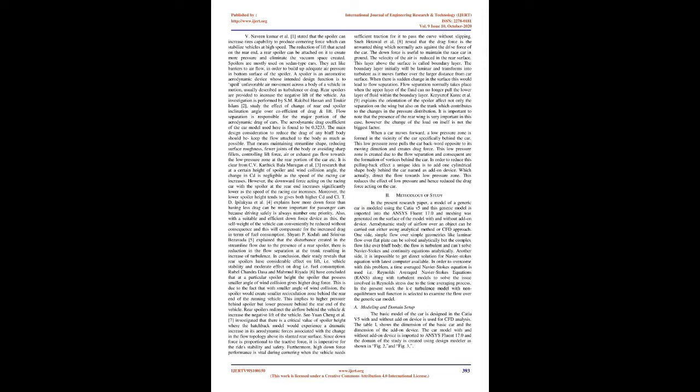A spoiler is an automotive aerodynamic device whose intended design function is to spoil unfavorable air movement across the body of a vehicle in motion, usually described as turbulence or drag. Rear spoilers are provided to increase the negative lift of the vehicle. An investigation was performed by S. M. Rakibul Hassan and Tokar Islam to study the effect of change of rear-end spoiler inclination angle on the coefficient of drag and lift.